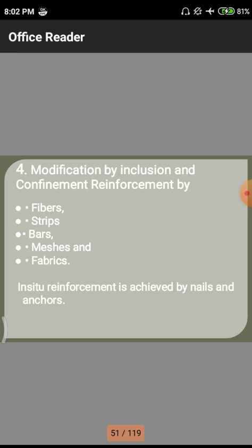Likewise, in soils also there may be some sort of linkage from one layer to another layer. If there is any disturbance between the layers, shear will automatically occur on those particular layers. The total layer will run off easily whenever there is a huge amount of storms and rainy conditions applied on the particular soil material. So to avoid those kinds of unevenness or irregularities in those soils, we need to use bar-like materials to create a proper bond between them.